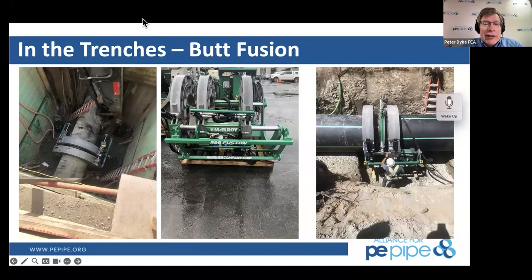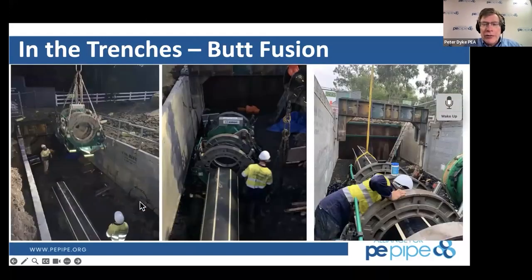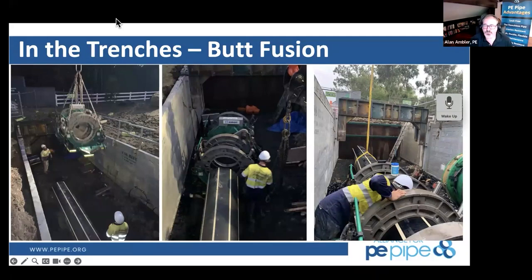So that on the right looks like about a 54-inch diameter. And these really large McElroy machines then get down to the 2 jaws, and they require extra machinery to help elevate the pipe or other equipment so that it doesn't apply torque into that fusion zone during a fusion. That's right. So good observation, Pete. When we get into the really big pipe and we start to see the larger McElroy equipment, that equipment is going to do a lot of the work for you because it's big pipe.